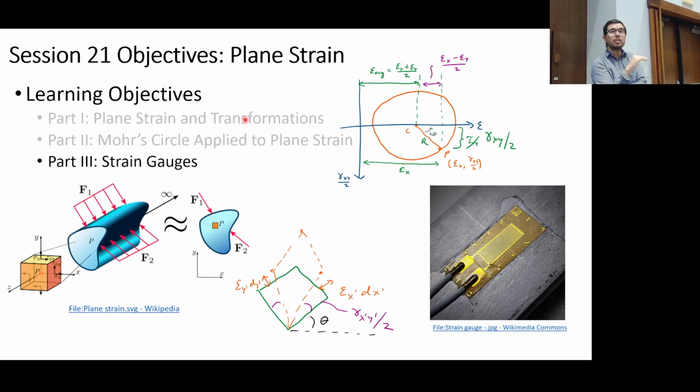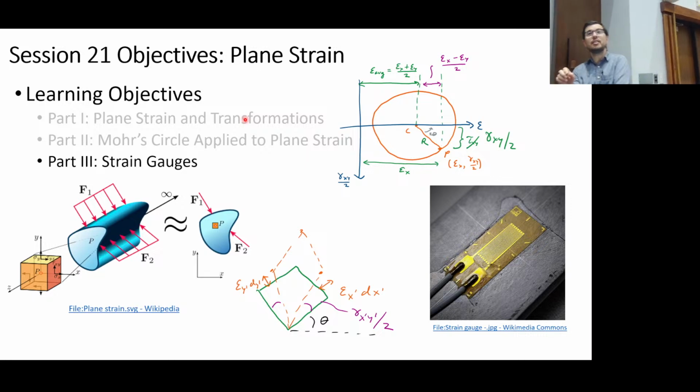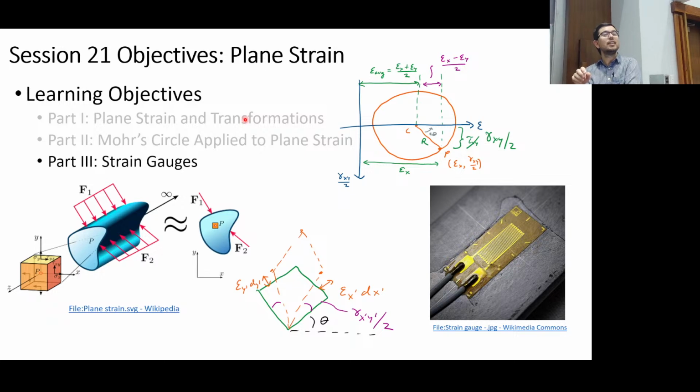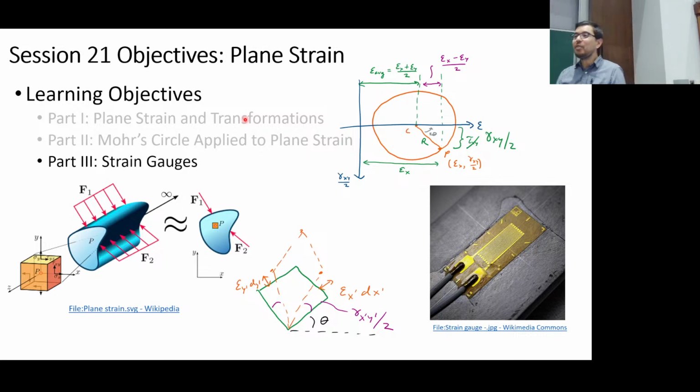So I completely used math there. Give me some more math that would indicate that the stresses can be the highest at the surfaces. Hold on. I know you're all thinking, what's another situation where the stresses are the highest at the surfaces? Yes. Torsion, right? Tc over J. We purposely use c as the radius. So the stresses are going to be highest when you're twisting.